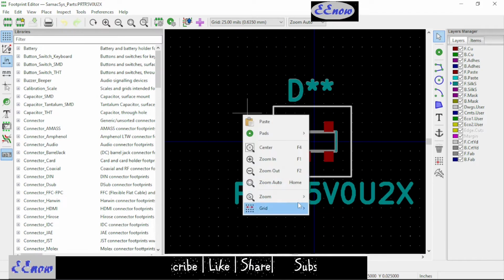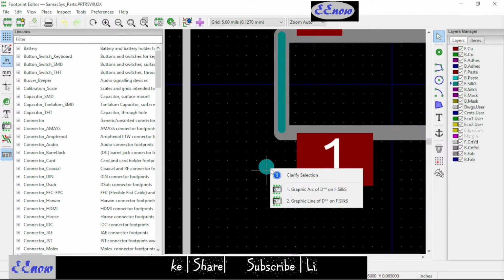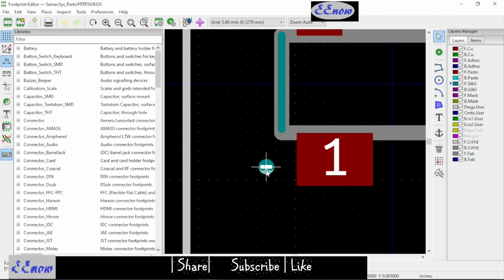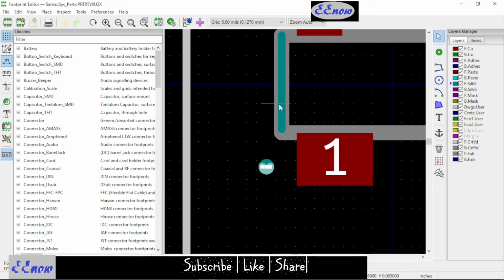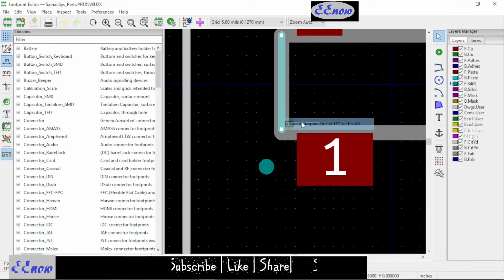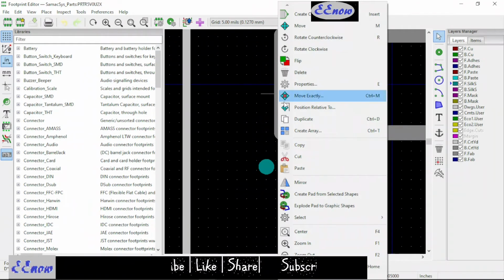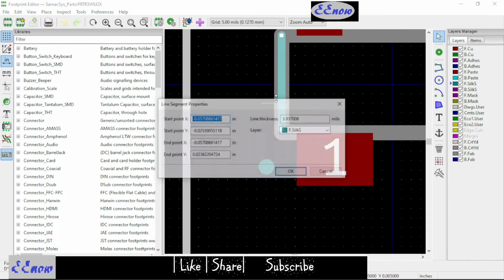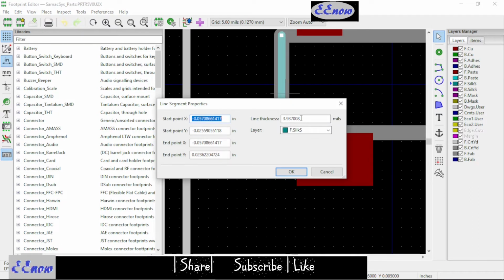Let's change the grid here. What do we like? Let's go to 1, maybe 5. I don't know. Okay, so silk screen. Okay, so the line thickness is 3, right? I think that's bad. Okay, this one is this line. Select, right click, properties. You can do it like that, or you can do it like select it and click E, right? So let's make it 7, right? 7, a little bit thicker, right?